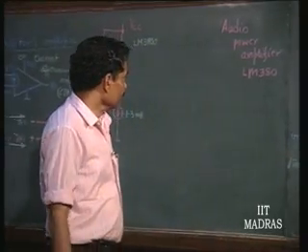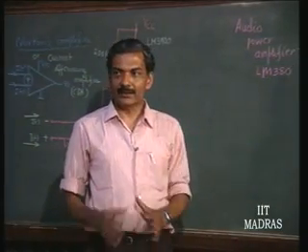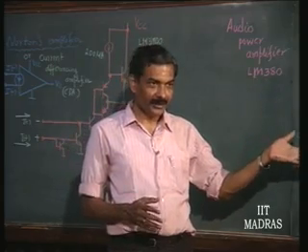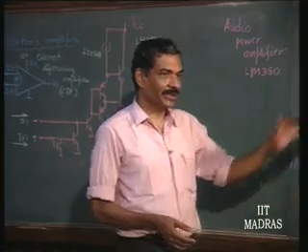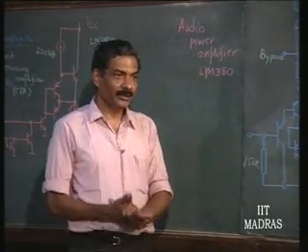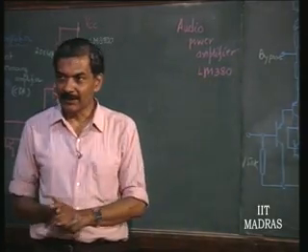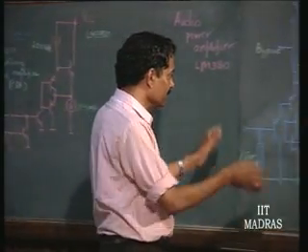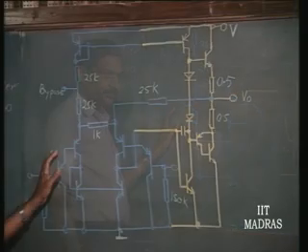So, let us see the strategy adopted in all these amplifiers. We will see some kind of similarity between this and whatever we have done so far. Right? This is supposed to be a voltage amplifier. And obviously, the input stage is again the good old differential stage, and since it is going to be designed for a specific gain, that is going to be a feedback amplifier. So, it is true that this is a differential amplifier input stage with negative feedback.